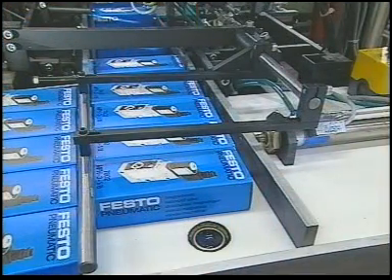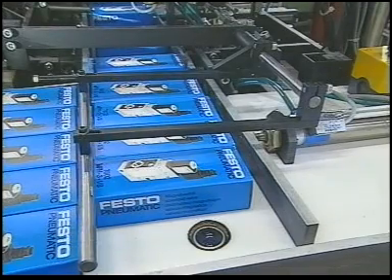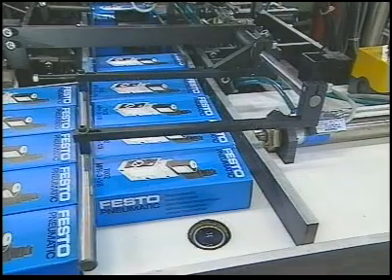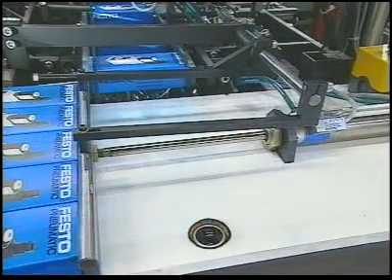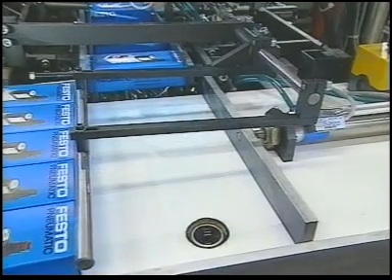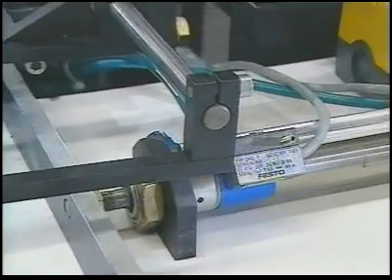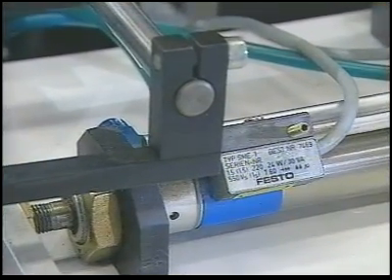The function of this electro-pneumatic slide unit is simple. When the optical sensor signals that 5 packages are present, the piston extends. When it reaches the extended position, the valve is reversed and the piston retracts. As only one condition needs to be fulfilled for each action, the valve can be directly controlled by the signal element.